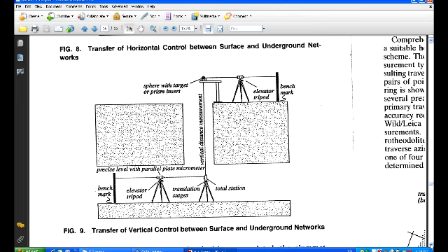And then we have to get from the center of the instrument over to a benchmark. And that is done by using the second level placed in a way that when the telescope of the total station is set to 90 for a zenith angle, in other words, the telescope is horizontal, the level would be situated so that the center of the level is within the micrometer travel of the center of the instrument, of the total station's target or crosshairs, as I mentioned earlier.